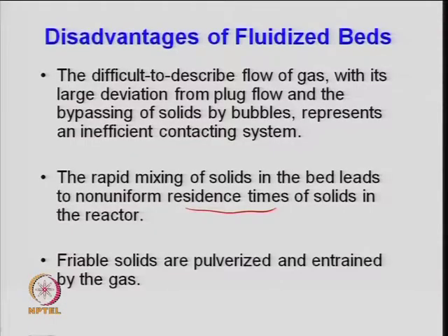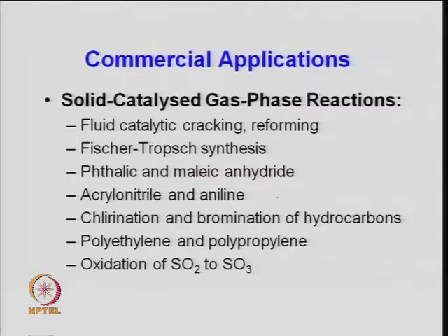And friable solids are pulverized and entrained by the gas, because when you find a particle which is very soft, it will crumble during the operation. Because of the attrition, it will become finer and then go along with the gas. So there will be a loss of the particle. These are some disadvantages, but fluidized bed reactors, as I said, are widely used.